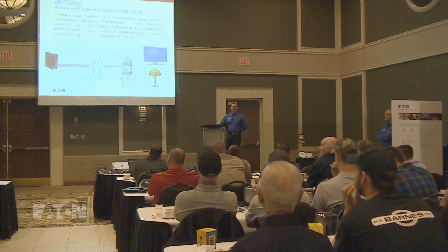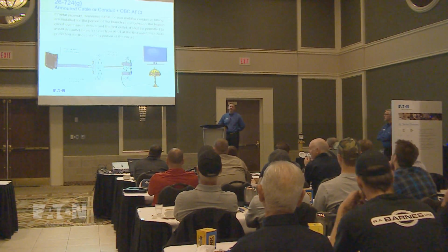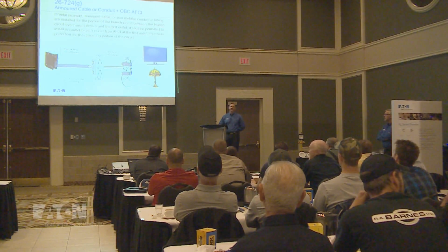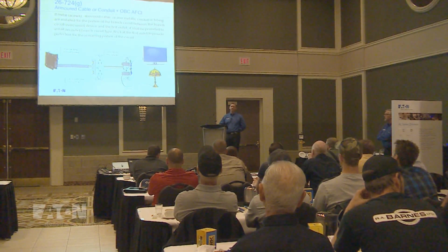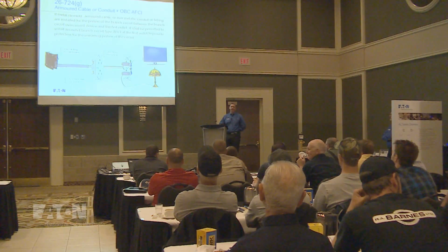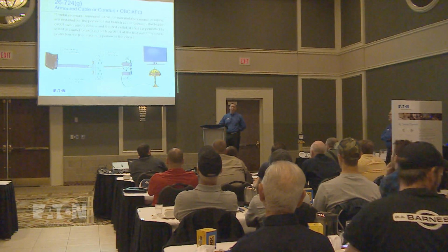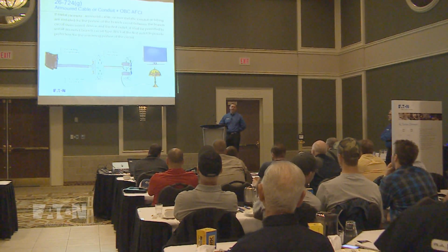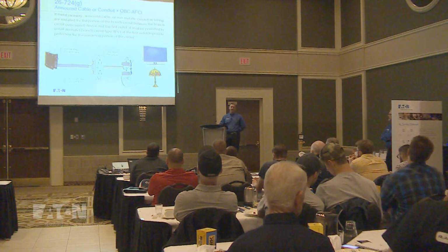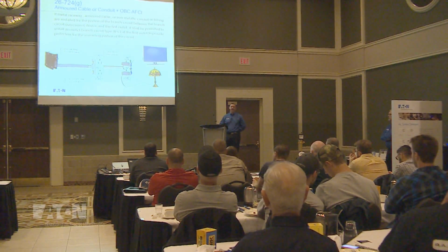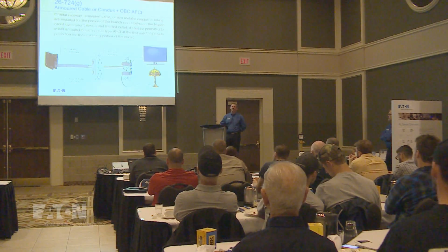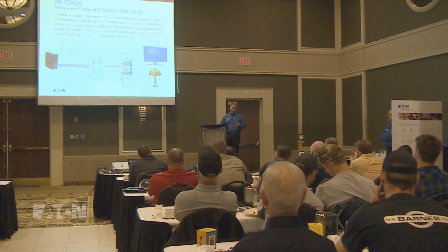So the comment from our ESA representative here is that they're currently allowing the use of this, and specifically when there's an older load center where you can't get an AFCI breaker, this is a great solution. And even though the implementation of the code isn't mandatory yet, they are accepting the use provided you wire it in this fashion, correct?